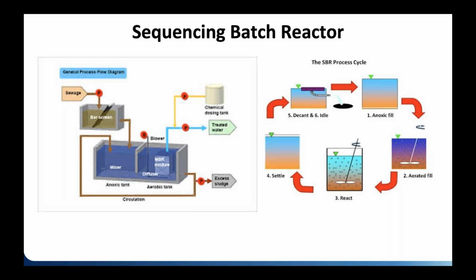The other one is what's called an SBR, or sequencing batch reactor. This is a little different because instead of having clarifiers and different things like that, they rely on fewer basins, one or two, and they treat water on a batch basis. You'll typically have screening coming in to take out any trash, sometimes grit removal, and then it will flow into a single tank. As the tank fills up with water, eventually it fills up and shuts off, and they have what's called an anoxic period.